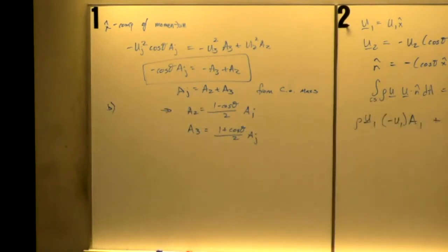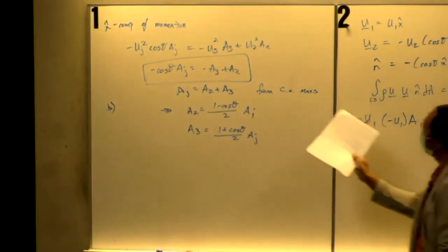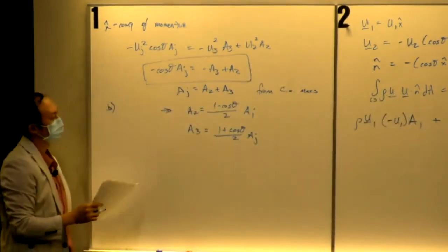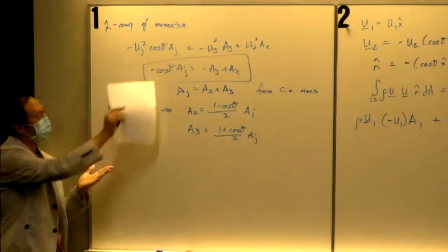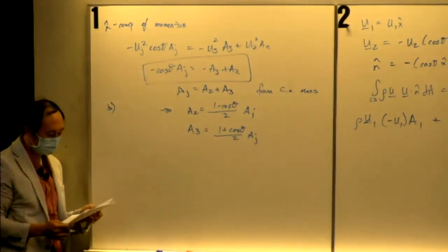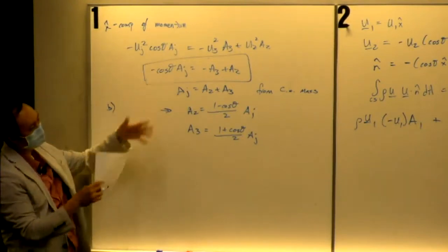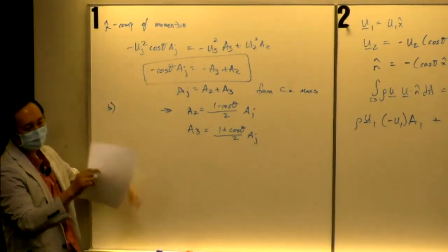And anytime you're looking for that second equation, it's either going to be conservation of mass or conservation of linear momentum. And keep in mind, conservation of linear momentum really has two equations: the x component and the y component. And here you're assuming there are zero forces in the x direction, so the fluid jets and the momentum contained therein basically balance out themselves.